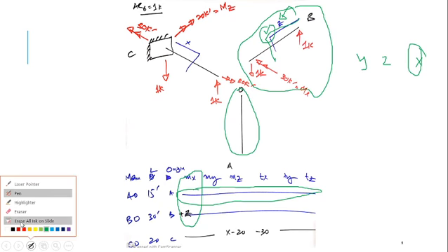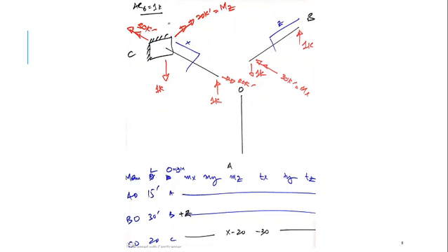Finally, I have this section. I have taken this section because this is in X direction, so the name of the section would be X. Here this 20 kip-foot should be balanced with an equal and opposite 20 kip-foot. You know that this is clockwise, so this would be anti-clockwise, so MZ would be minus 20 here.